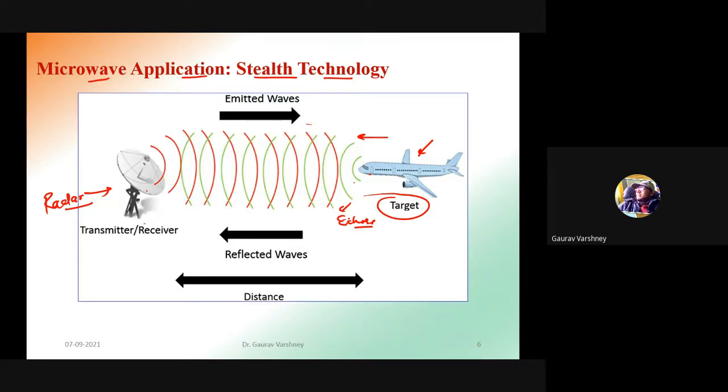Using the receiver section, the radar system receives that signal, and finally this signal is processed using a matched filter, low noise amplifier, and further devices. Using the Doppler effect, we can find the speed of this aircraft, its distance from the radar system, and related parameters. So this is the basic concept of the radar system.